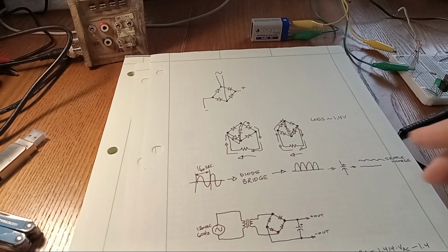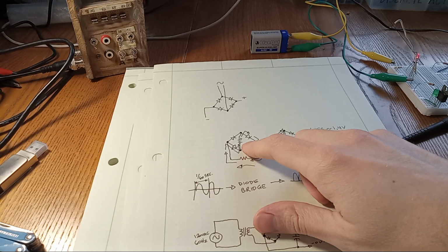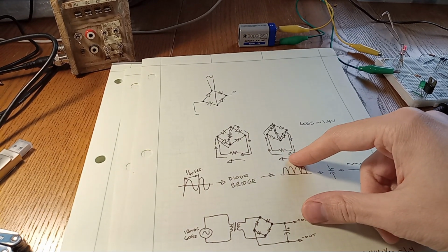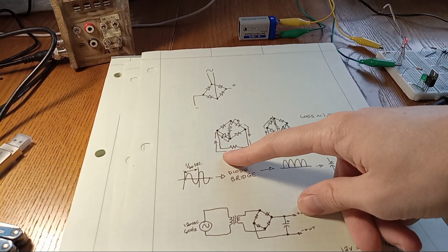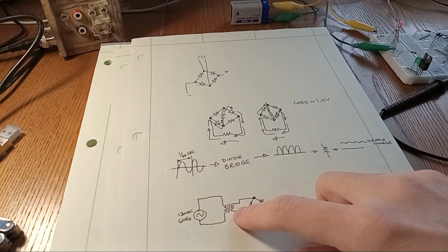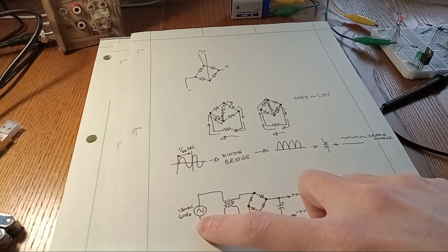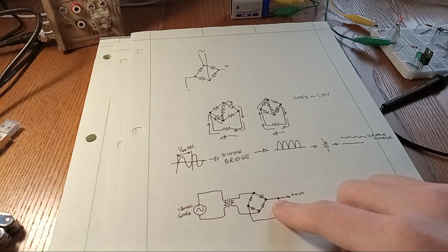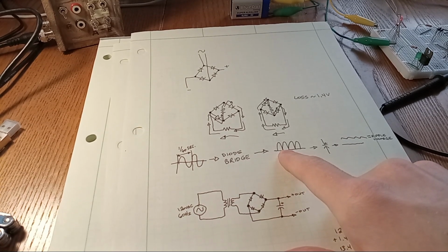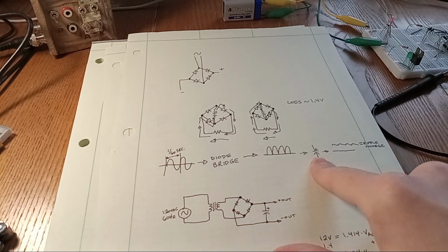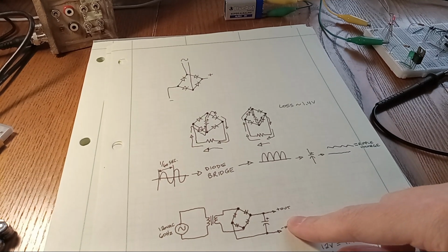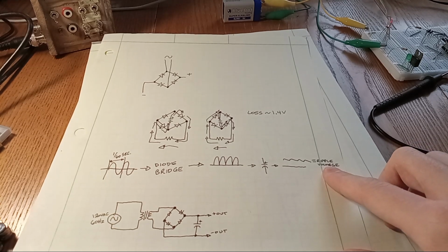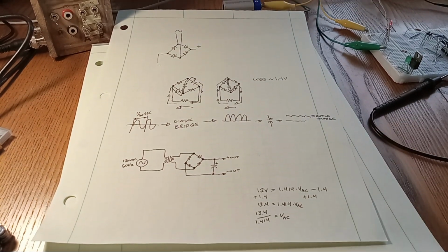Then we talked about diode bridges, how you can structure diodes in this diamond shape, and they will make it so that current always flows the same direction through the load. This can be used in combination with the transformer to convert wall power down to a lower pulsing AC voltage, which, through the action of the diode bridge, then creates this pulsing DC voltage, and combined with the filtering effect of a capacitor, enables you to get a constant, relatively constant voltage output. There is some ripple as the capacitor charges and discharges.